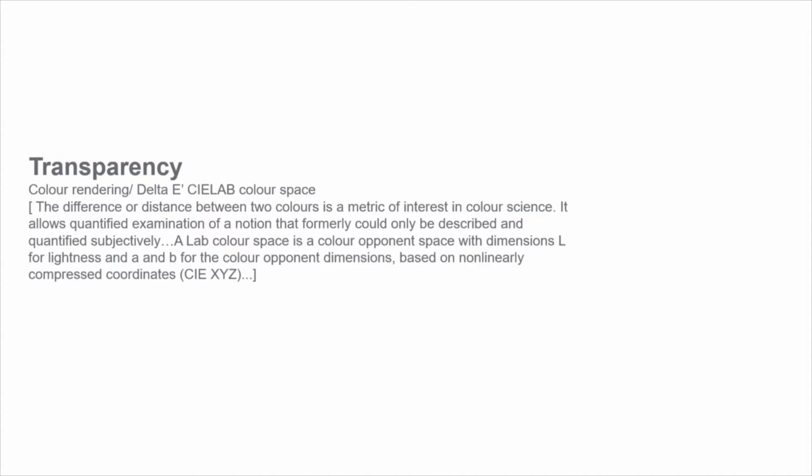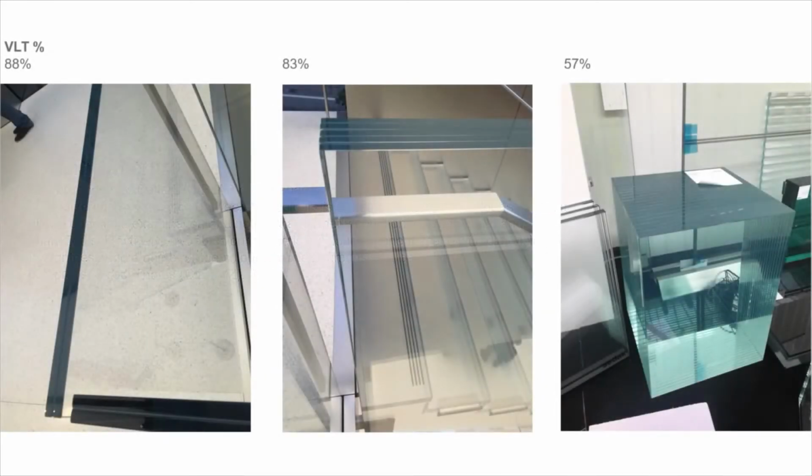And whilst glass does a lot of that, there's always a small portion that isn't transmitted but is reflected and absorbed. And both the reflection and absorption are important. The absorption because that has an effect on the appearance of color. And when we look at color, it really plays a very important role in the architectural use of glass.